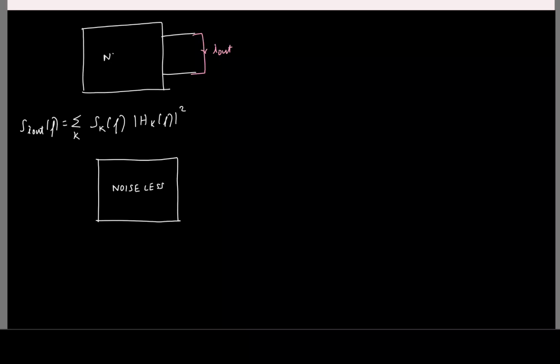So this was a noisy network. Basically we assume that there is no noise coming from the resistors or the MOSFETs, but the entire noise is generated due to an input voltage source. This was the input referred voltage noise we called Vn,in.